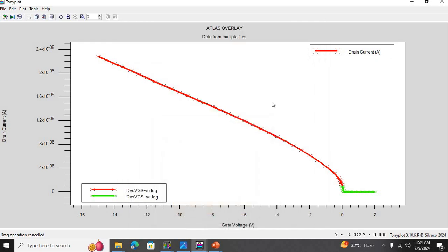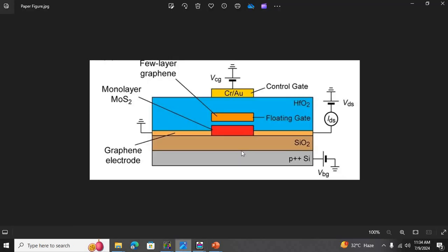After giving it a lot of thought, I think I've got a good explanation for that. So the first thing is that molybdenum sulfide is entirely different as compared to the conventional silicon based field effect transistor. In the conventional transistor, we have a substrate layer, and minority carriers are attracted from the bulk region towards the surface. However, in case of molybdenum sulfide transistor, we don't have the substrate region from which we can actually attract minority carriers towards the channel region. We have the silicon dioxide. Electrons cannot flow from this P plus silicon layer to the channel through the silicon dioxide layer.